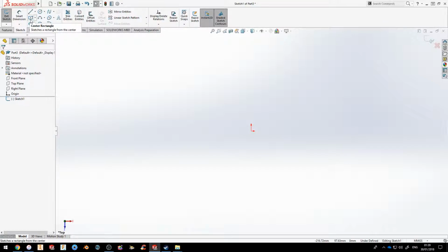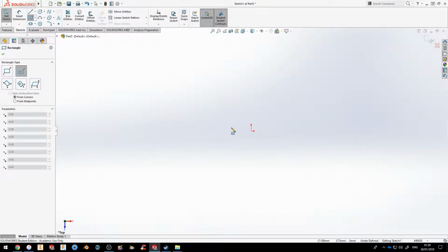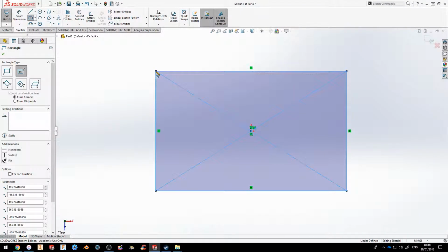and then if we're going to make a box, you want to just come to this top tab up here, and click the little box shape, and then click on the little drop down key, and then go to Center Rectangle. And click the center point. You'll notice the center point because the little orange dot will come up. And just drag outwards until you're happy.